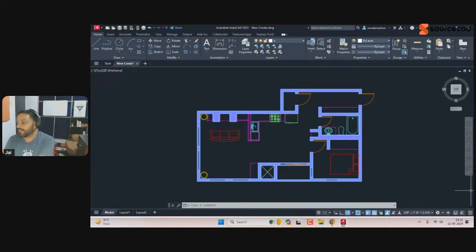Okay, so I have the last question here, how to edit ZWCAD drawing in AutoCAD. Well, you can directly edit the drawings made with ZWCAD. Drawings made with ZWCAD will just show a warning when you open it in AutoCAD that it's not created with default Autodesk program, but you can ignore it. Okay, and after that, it should work as if it was a simple AutoCAD drawing.